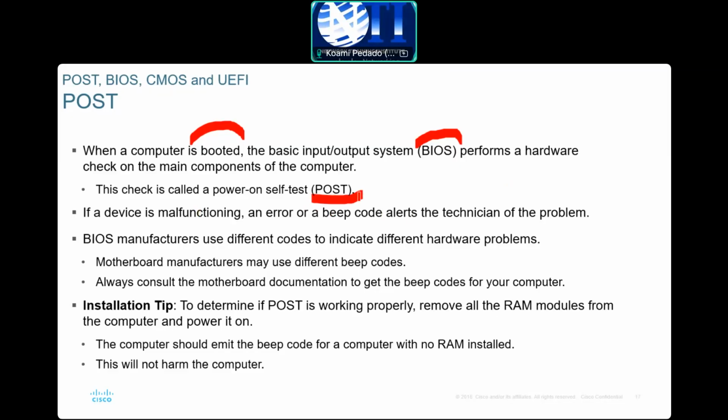It will check to see if this is working good, this one is good. Every component of the computer is good. If something is missing, you hear a kind of beep. Like if it's memory, it will go beep, beep, beep, 3 times. If it's like a keyboard that is stuck, or one key is stuck, you hear the beep continuously, beep, beep, beep, never stop.